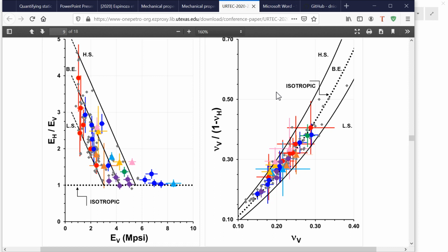But nonetheless, we can see that, as we expect, as the Poisson ratio increases for a given formation, the effective lateral stress coefficient increases, and it depends on the anisotropy of the rock whether that goes a little bit to higher values or to lower values.